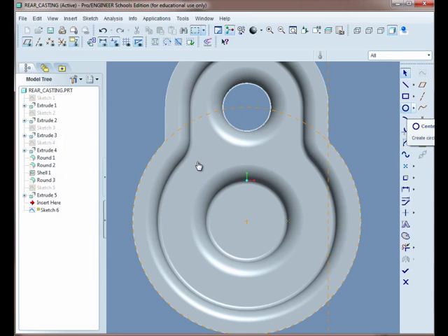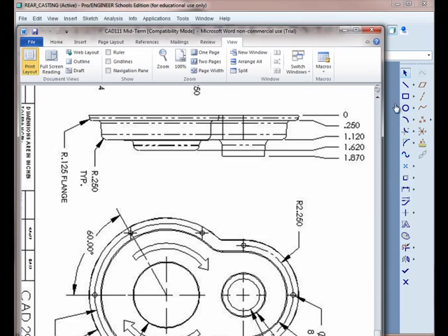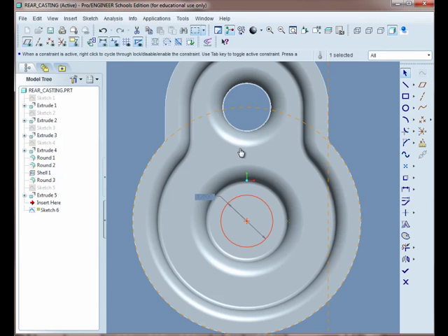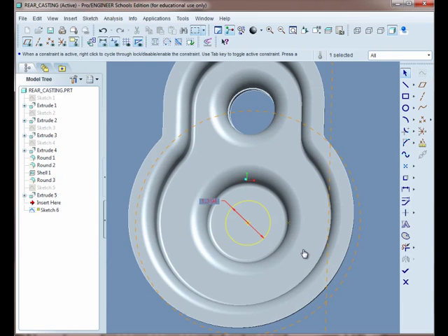Now we could take a circle tool, and if you don't have that as a reference on the outer edge, be sure to use concentric, and then you can select the edge. But since I have that reference, I could just go ahead and draw this out. Now let's look at this here. This hole needs to be 1.394 in diameter. So 1.394. And then we know there's going to be an offset of 0.25.